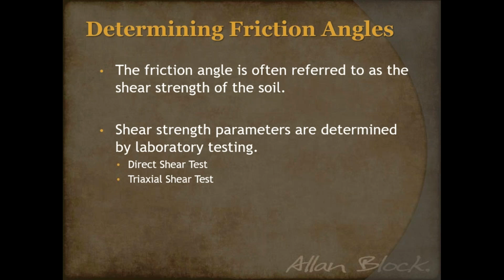And a college professor of mine often referred to, what are you looking for? If you're looking for shear at an angle, 45-degree angle, which is a lot of times how soils fail, triaxial shear might be a little bit better. But if you're looking in the horizontal plane, direct shear might be better. But really, it comes down to the time, the scope, the budget. Gets into the geotechnical engineer's expertise.